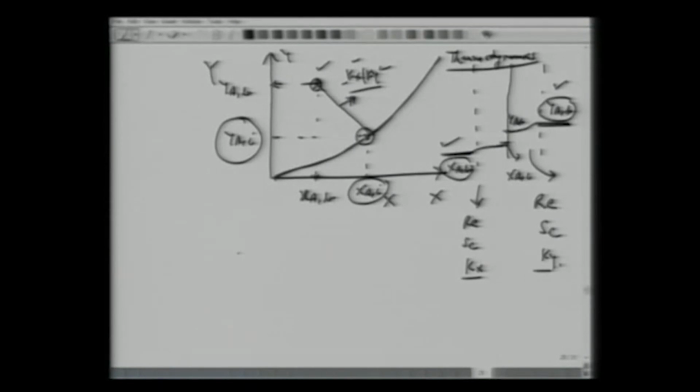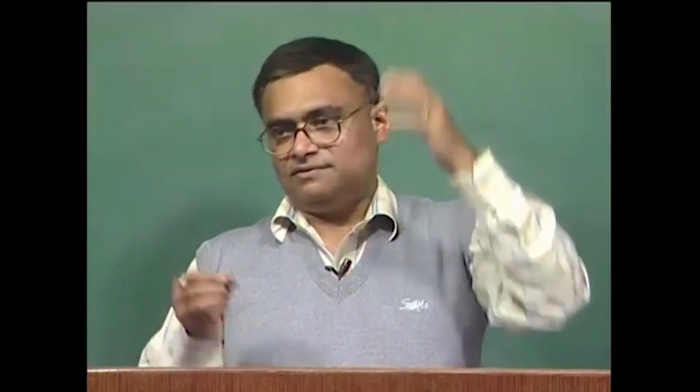And now the problem comes here: what are these interfacial concentrations and how can we measure them? It's very difficult. If you have a flowing system, with a gas phase, say sulfur dioxide goes from the bottom to the top and water trickles from the top to the bottom, and we have the interface, right? If you are asked to measure the concentrations, all we can do is take samples of gas from the bulk or samples of liquid from the bulk.